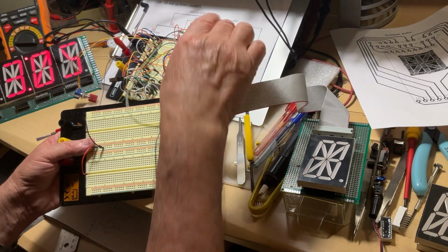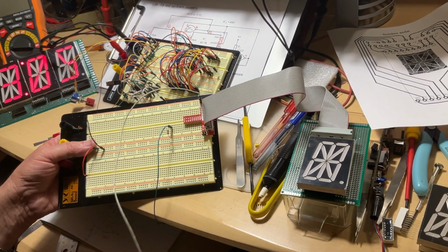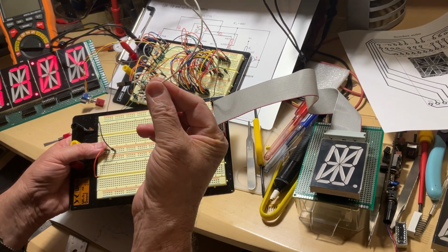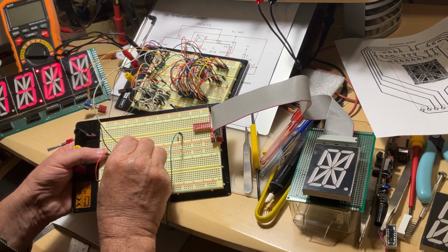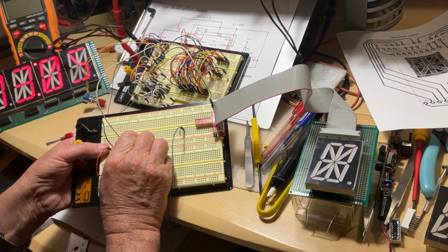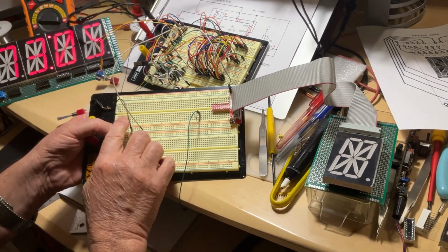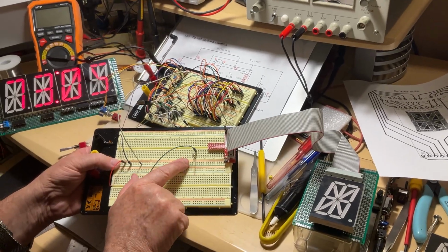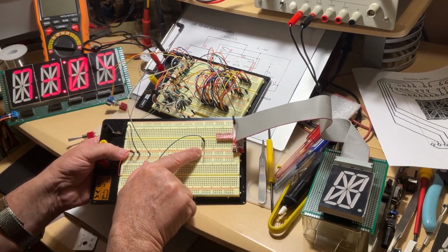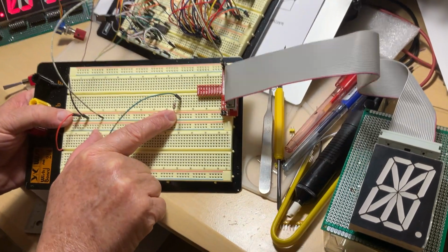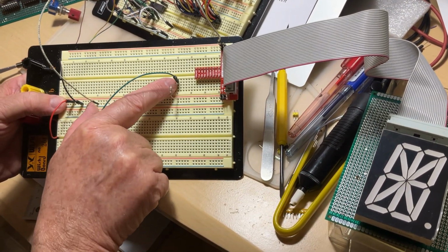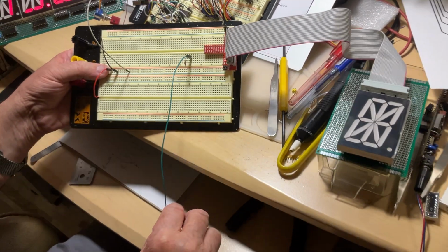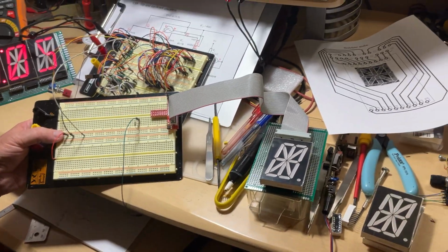So before we talk more about the construction, let's find out. I said this is a common cathode, so here is the common. Because it's common cathode, I'm going to plug this one to the negative. Remember that anytime you power an LED, you energize an LED, it has to have a limiting resistor. So there is a 100 ohm limiting resistor right here with a piece of wire.